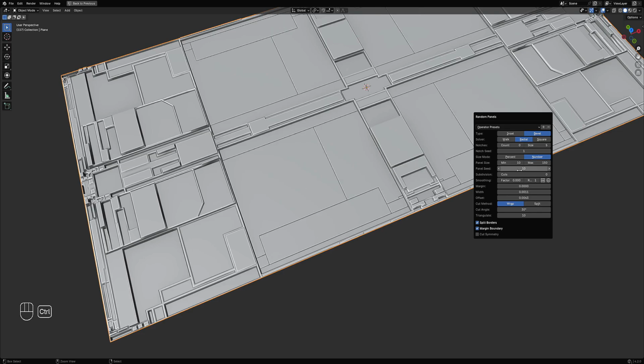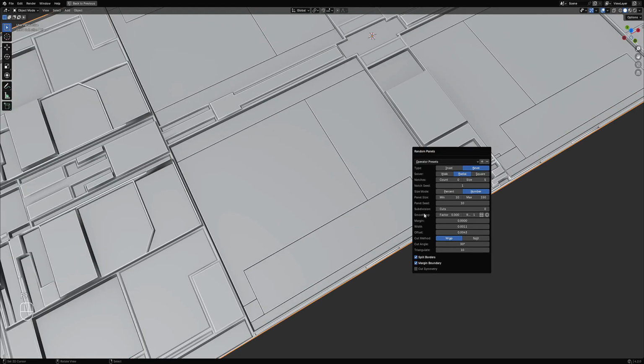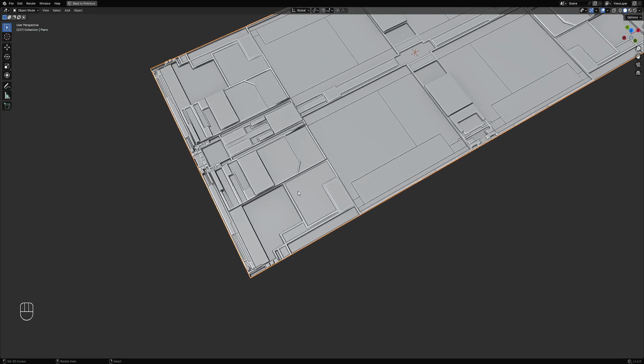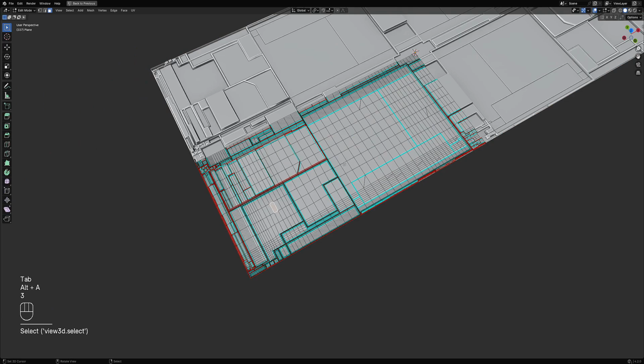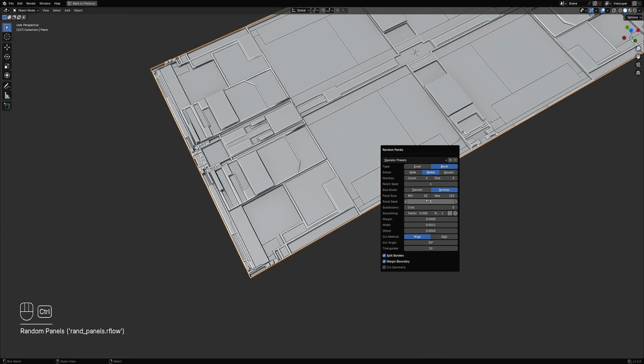So for the larger areas here, we can just use the bevel. We can avoid splitting the borders, which in this case is a bad idea. Okay, it's right here. So I'm pressing the Alt key event. This is really helpful for flat faces and also curved faces, which meet the sharpness angle threshold.